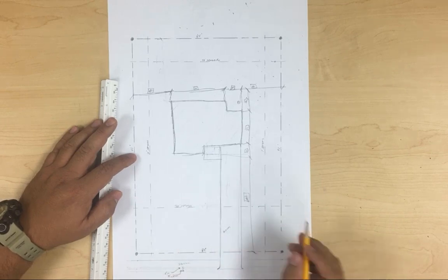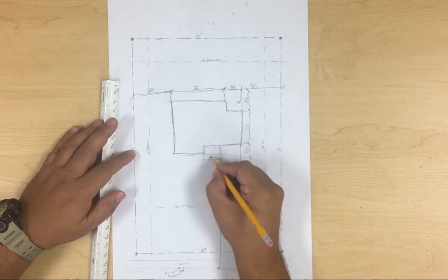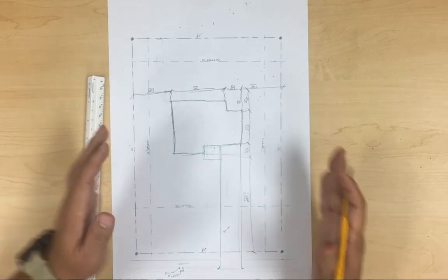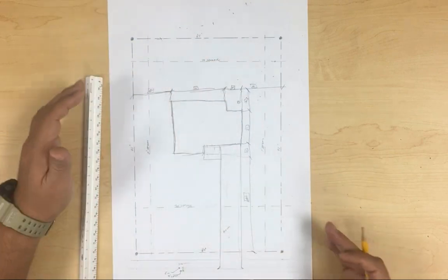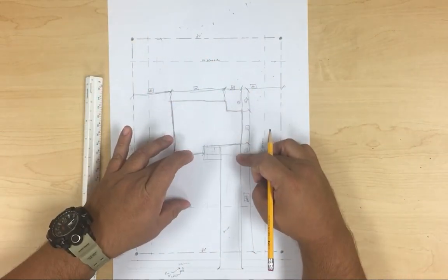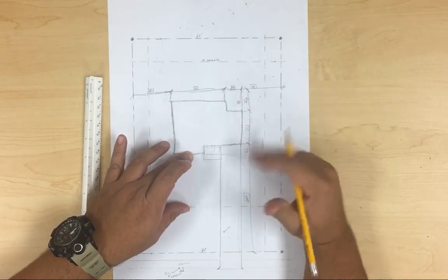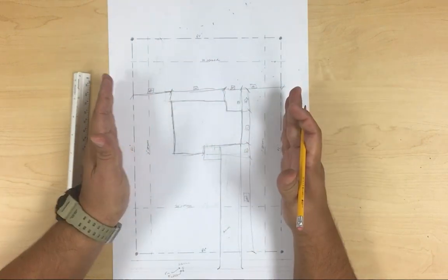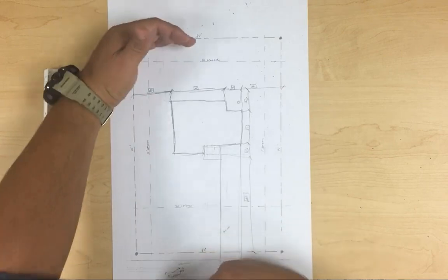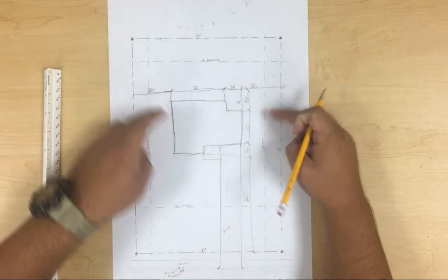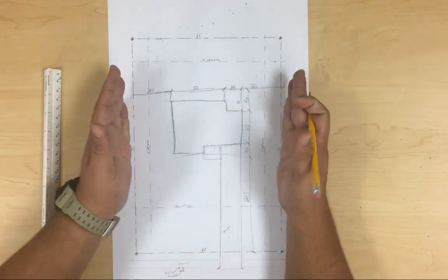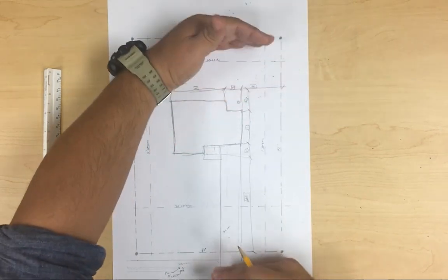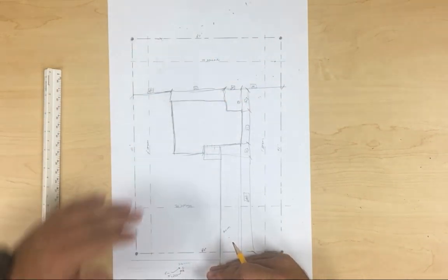All right, and then driveway, and you can put sidewalk too if you want to. Okay, so now again, property, we have it. Setbacks, we can respect that. We put our house and the property where we want it according to the design. We have to dimension it, take into consideration the width and the depth of the property. So we have dimensions here, and we have dimensions tying to the ends, and also to the front and back of the property.